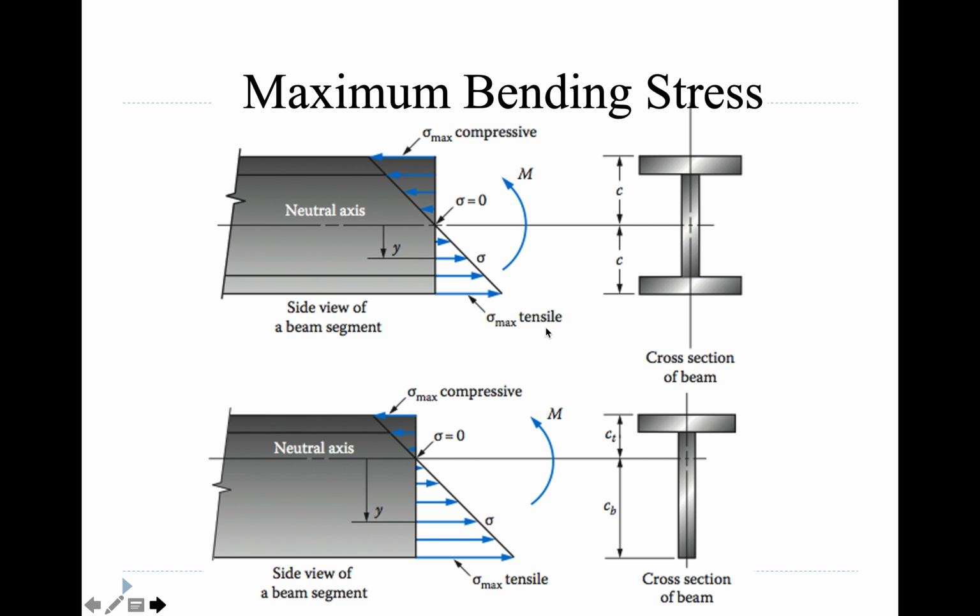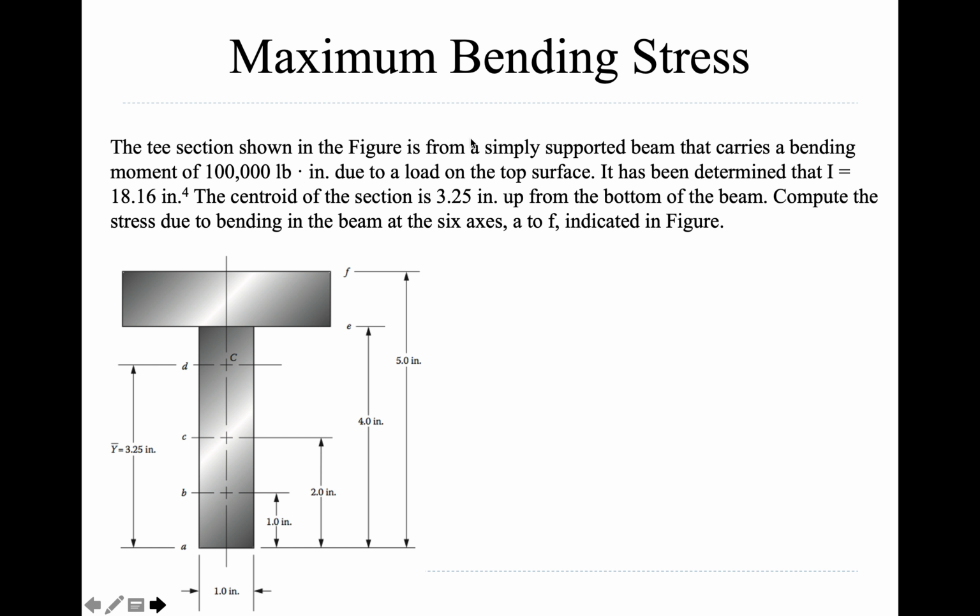So, if you combine steel with concrete, by putting the steel in the heavy tension side, then you've created a reinforced concrete structure. And that's what all concrete in basically the world is: it has steel in it to combat the tension forces. Combine the superpowers to form one super material called reinforced concrete. But it's primarily only on the tension side, because the concrete's like, hey man, I got it up here in the compression side. So this is the principle that we're trying to solve for.